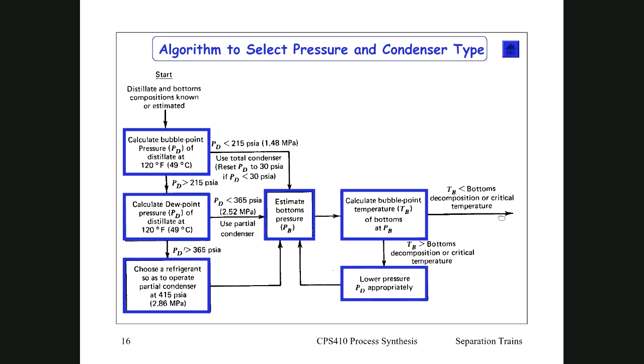If that temperature is too high, then you would lower the pressure appropriately until you don't get decomposition. What that's going to do up here is it's going to lower the temperature of the distillate, and then you would have to use refrigeration.